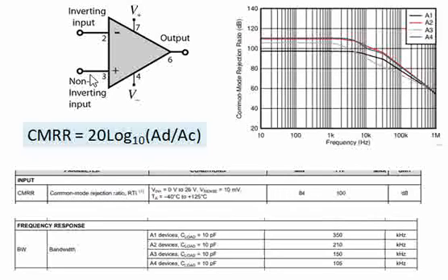When you come to the op-amp, ultimately it is a difference between them, and the common mode voltage should get rejected, right? That means the common voltage that is there should get negated, and only the differential signal should be taken. This is the simplest way we can explain it. So common mode rejection is a very important parameter for operational amplifiers.